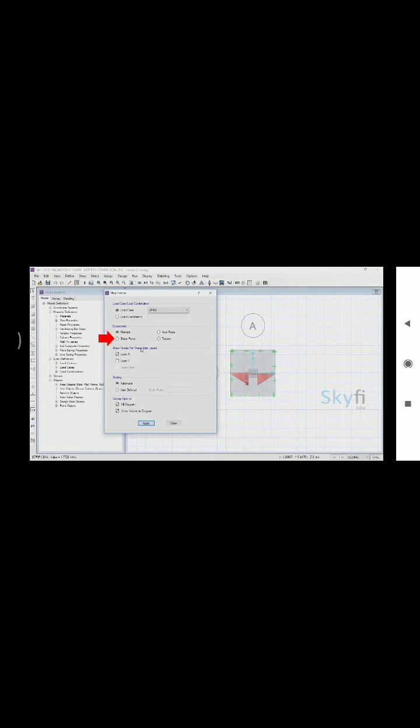Select the Shear Force option. Select both layer A and B, and click on Apply. This time, the shear forces diagram along both the strip layers A and B, that is along the X and Y directions respectively, are displayed. Here too, you can hover your cursor over the design strips, to check for the shear force values at every point. Uncheck the layer A option, and click on Apply, to see the values only on layer B. In this way, you can try out with the other options. Click on Close, once you are done.